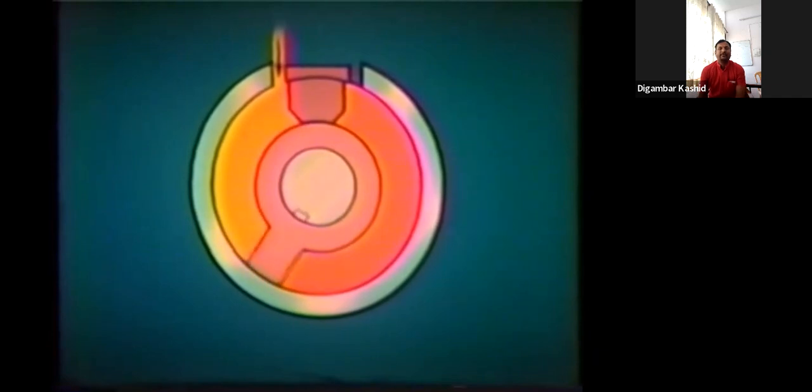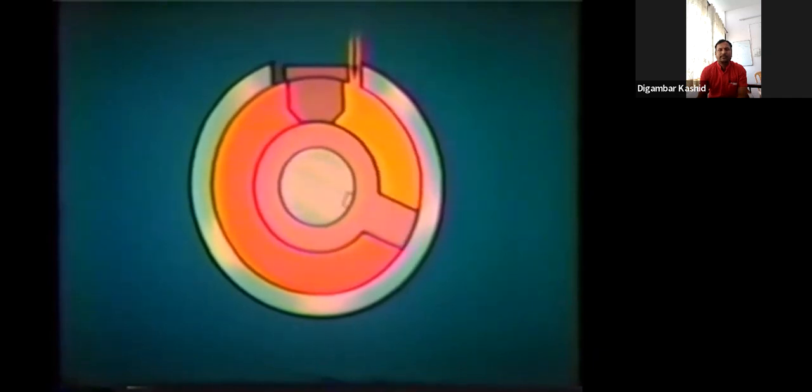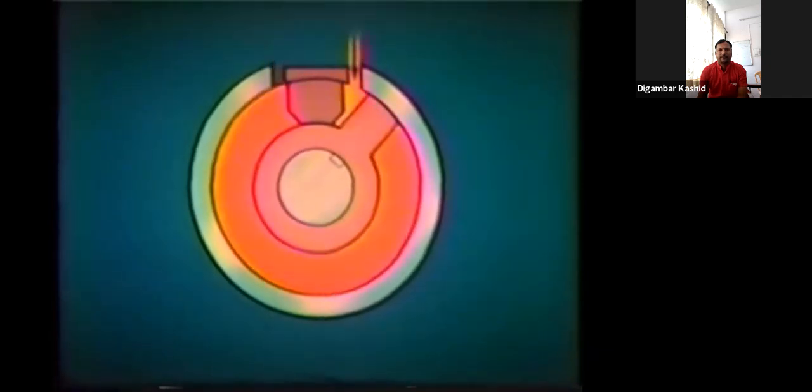A fluid pressure differential between the chamber compartments acts upon the vane to cause shaft rotation through an arc. The majority of rotary actuators are constructed with 1 or 2 vanes, but they are available with 3 or more vanes for special applications. The rotary actuator, simple and efficient.